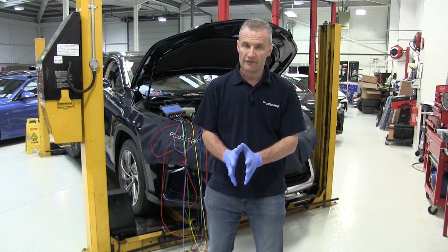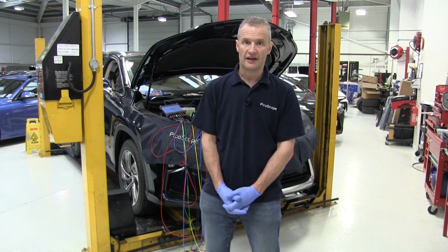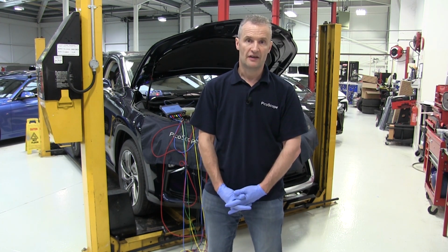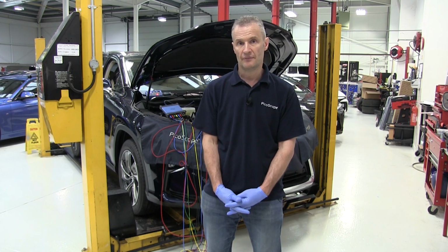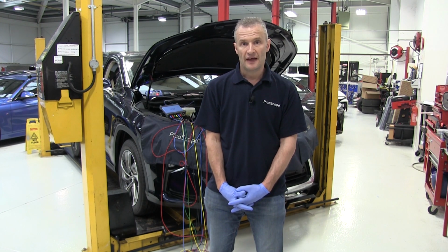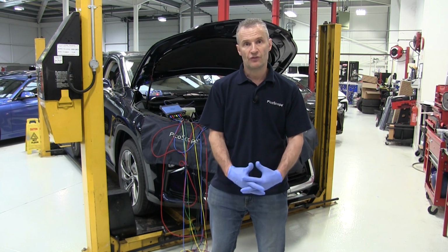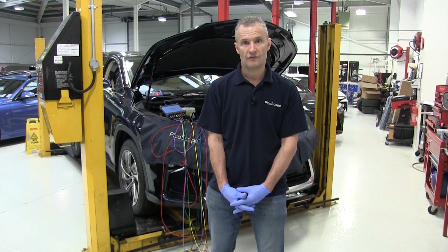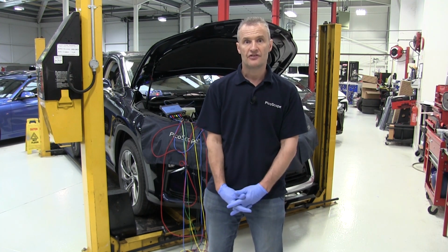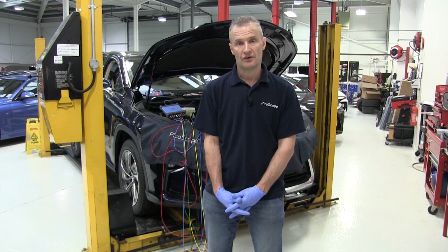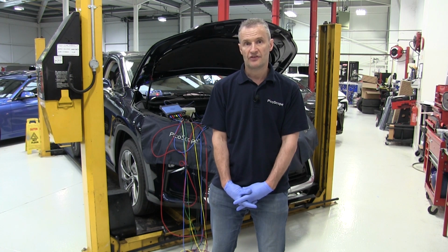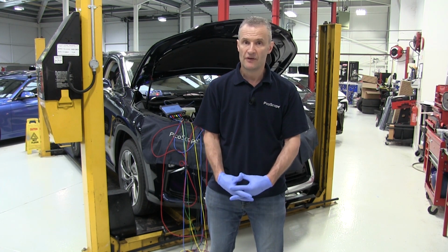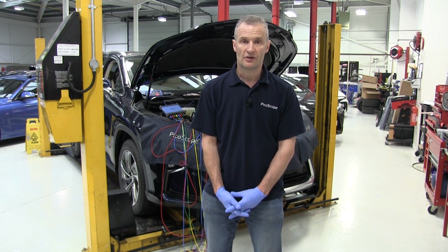So remember, if you're doing a comparison, VVT controllers disconnected so that the cams return to their default or rest position, whether that be full advanced, full retarded. You'd have to refer to the manufacturer features for that information. Once you've done that, then you're comparing apples with apples. So this is your faulty vehicle with the cam correlation, VVT controllers disconnected, against your good vehicle, your donor vehicle, whatever it may be, or post-fix. Once you've captured that event, post-fix, again, ensure that you are keeping variables to a minimum, VVT controllers disconnected.